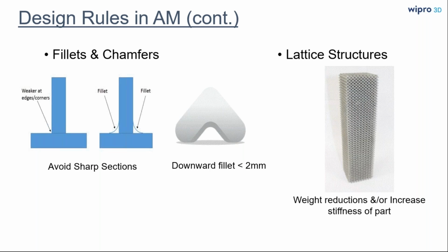And again, chamfers are a unique capability of 3D printing, because we are working with extremely fine lasers and extremely fine powder, and oftentimes incorporate these in our designs and drive down the wall thicknesses. So in case we have a bulky part of 5-6 mm thickness, we can make the wall thicknesses 0.3, 0.5 mm and introduce these lattice structures inside the geometry, which should drive down the weight and increase the stiffness of the part, which can be useful in the aerospace or sectors which require the parts to bring down the weight from a functionality point of view.